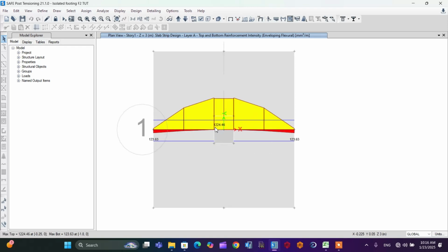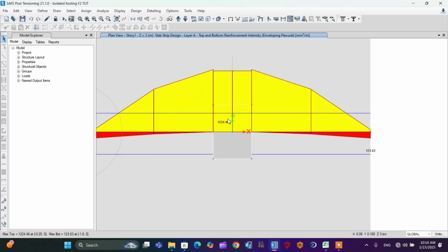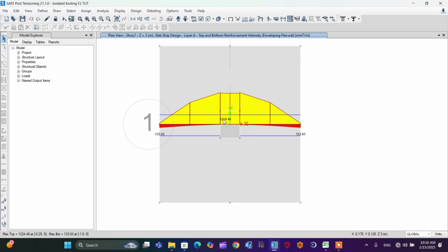After that, you have to get the maximum area of reinforcement, that is the bottom reinforcement, like this. This is the bottom reinforcement. I have to take it as the bottom reinforcement. This is because the moment is downward. I will show the moment. So you can divide this into any area of reinforcement, and you have to get the total area of reinforcement and spacing of reinforcement. We will calculate it together on an Excel sheet.